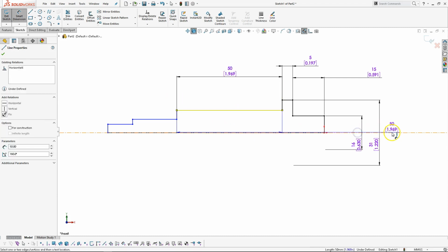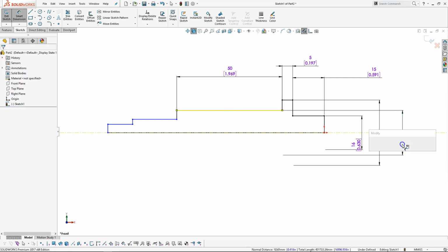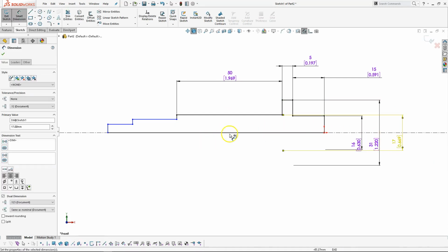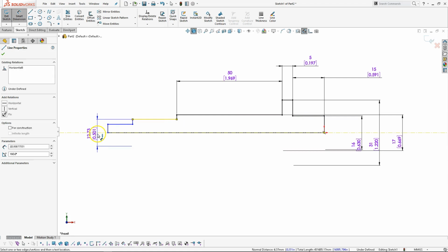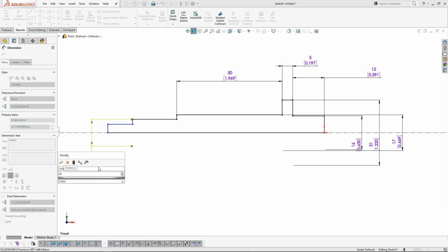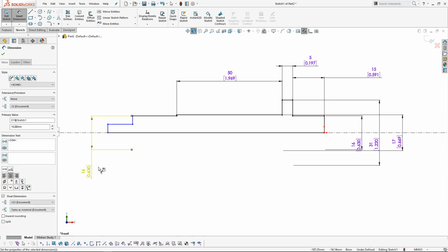Let's see, this was 17 millimeters for the through, so just a little bit bigger than the shaft. And then this is going to end up being a 16 millimeter by 1 pitch thread.